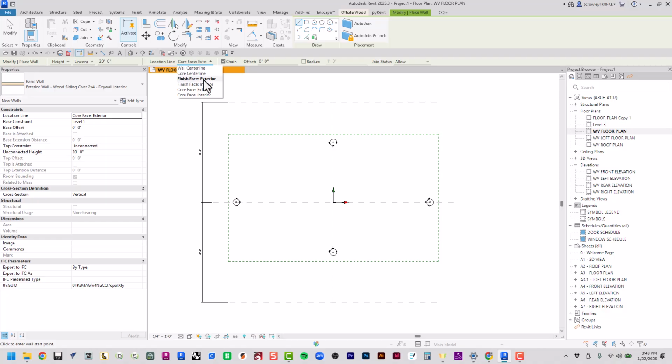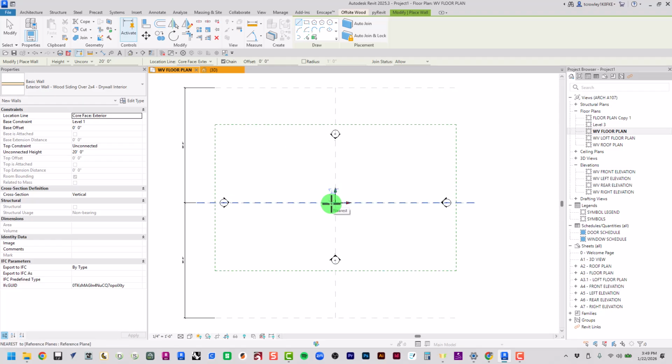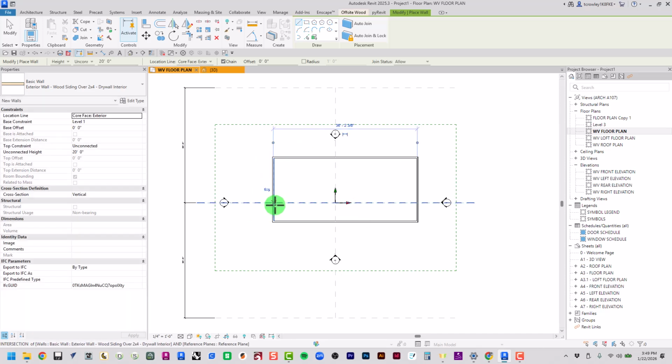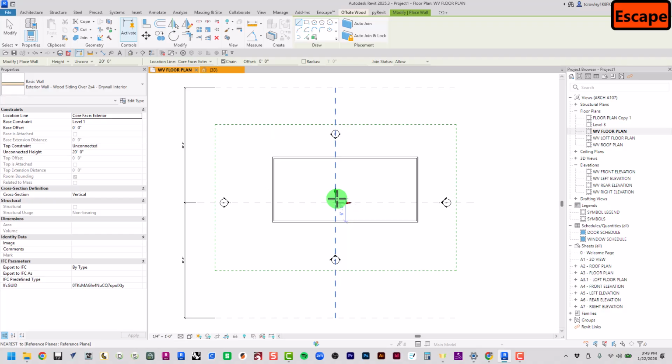And this is a very rectilinear plan. So I'm just going to draw from point A to B for my first wall, and then from here to here, here to there, and complete the rectangle. Let's end this command by hitting escape a few times. And the first thing I want to do here is under annotate, aligned, I'm going to dimension all of these walls. So starting with this wall here to here, and then from here to here. And what this allows me to do is understand the proportions of this rectangle that I've drawn.